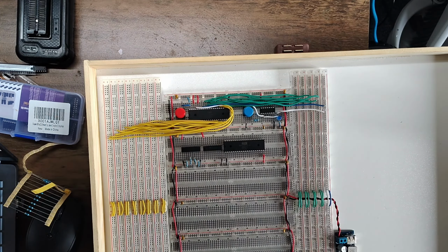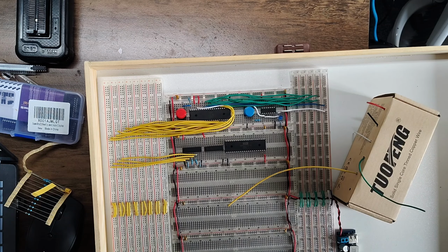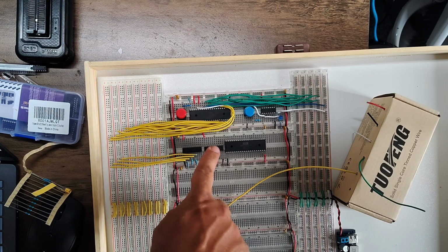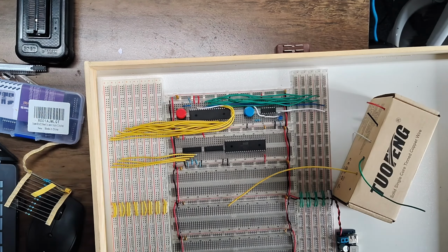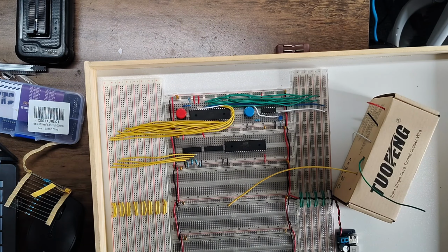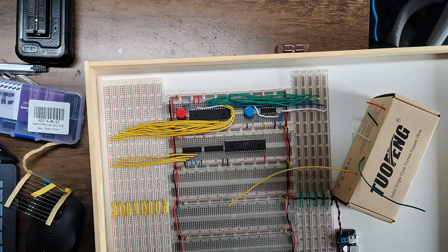And there we are. The first 4 address lines are connected up. So the first number of our address, if it is 6, it will go to this chip and it will manage to get out and into the next chip. So the next thing I need to do is the next 8 bits, which are all zeros. So I can connect now. I don't actually need resistors if I connect them to 0 volts. But I'm putting in resistors 1 because it looks nice, 2 because they're cheap, and 3 because it gives me the flexibility to put in a different address in the future if I wish to. So another 8 resistors all going to 0, so let's do that.